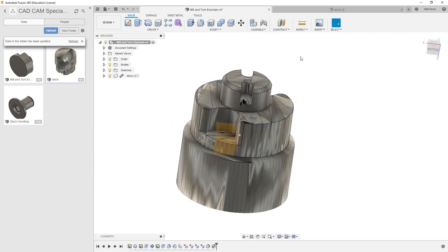So there is a little bit of an additional workflow that has to happen when we're trying to utilize these STL files. While we could directly put the file location of that STL and use it for rest machining and checking against the file, we do need to ensure the scale and the orientation are correct to ensure that the results that we're getting from rest machining are correct as well. So depending on, again, the complexity of the file, it might make more sense to export an STL from simulation, or it might make more sense to come back into the design workspace, copy the original body, and modify the features to represent the current version of stock.